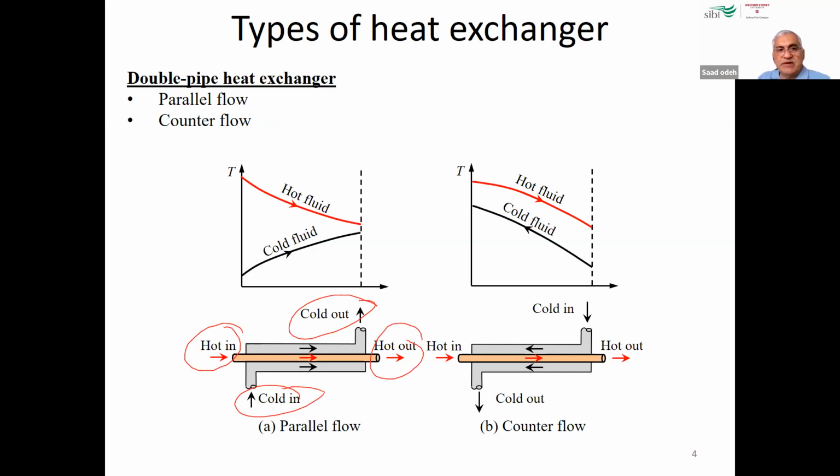So we call this parallel flow. In parallel flow, the difference between the inlet of the hot fluid, T hot in, and the inlet of the cold fluid is quite big, while at the exit, the difference between T hot fluid exit and T cold fluid exit is small. So this is parallel flow.